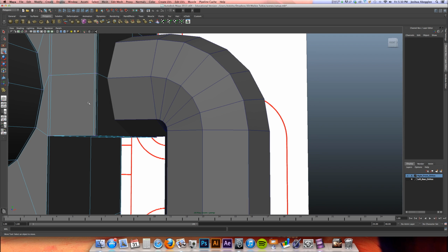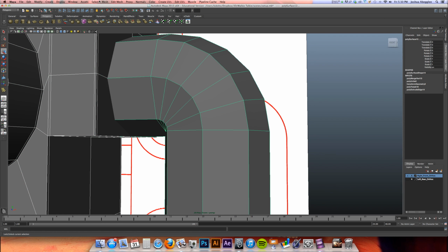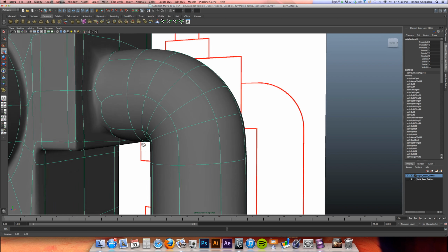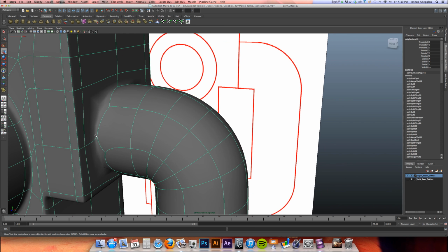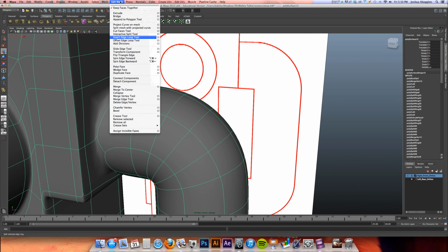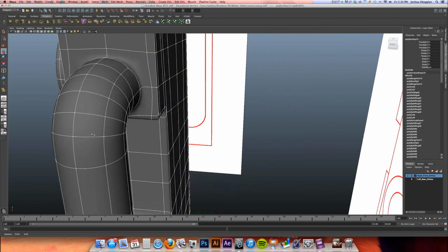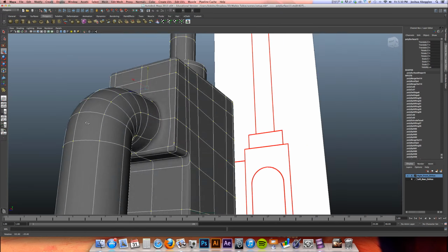So let's go ahead and select both of these objects in object mode. I'll start with the base, select the handle, click on Mesh, come down to Booleans, and boom, Union. All right, you can see we need to do a little cleanup. This vertice should be connected with that vertice. Now just having the object selected in object mode, I can just go ahead and hit Merge, and for the most part, it should do the job.